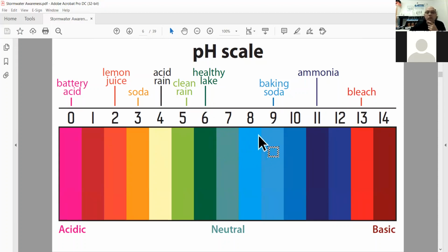This particular range is good for lakes. This is just an extremely healthy lake representation. Different treatment technologies may require different pH ranges for effective contaminant removal. For example, a popular coagulant used in treating construction stormwater runoff is known as chitosan acetate. The effective pH range for this polymer is lower than 9 and above 5. At a pH of 10, the polymer just doesn't really do the job.